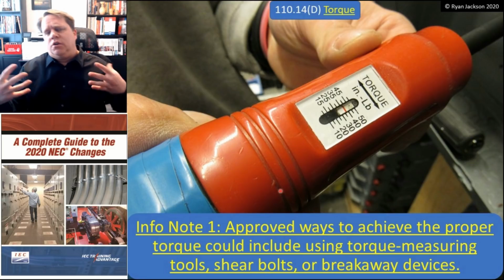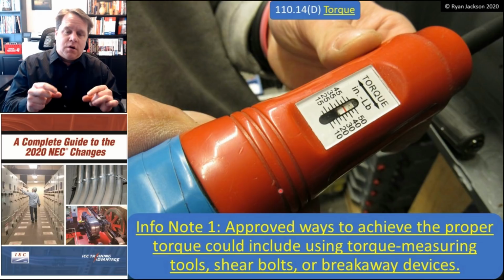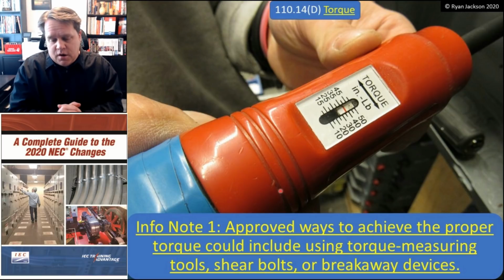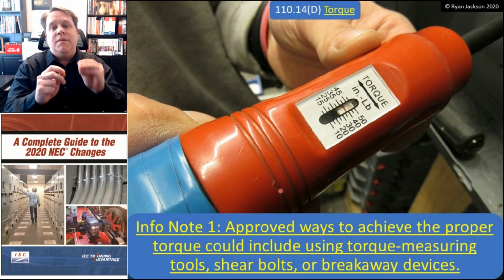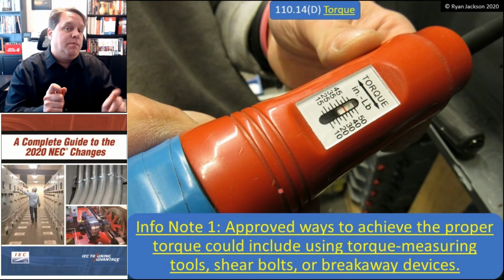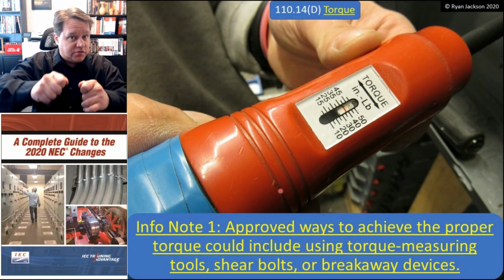If you go into a large commercial building that has structural metal, and look around at all the red iron, you might notice the high strength bolts. If you get there during construction, when they're putting in the high strength bolts, there's a little nub on the end of the bolt. And if you see this little nub, that means that it was not tightened correctly. That way the building inspector can walk around and from a mile away, he can see any terminations that weren't done correctly, these high strength bolts.